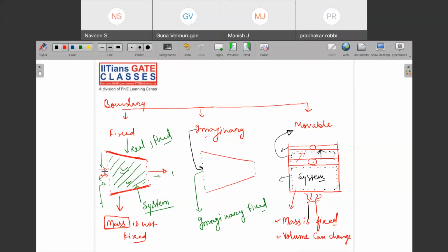But here can we see that mass is not fixed. Any lesser mass or higher mass can occupy depending upon their density, right? Why? Because we know that mass is nothing but density into volume, right? So depending upon this density, this mass can get varied. So these are the problems where we are studying compressible flow, like when density changes, mass also in particular region can get changed.